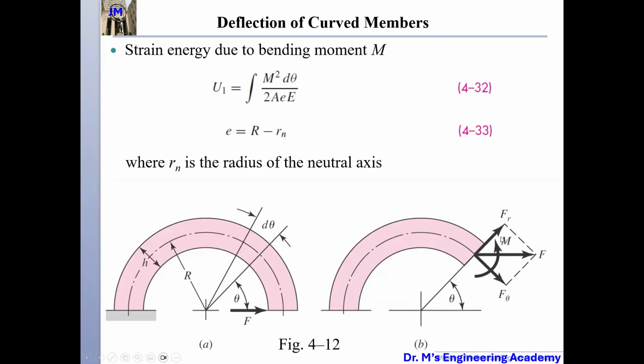So all these I r, I theta, and I am along with this I theta, because when we decompose this I into I theta and I r, the point of entry we move to the centroidal line. Okay, centroidal line, that means it is different from the neutral axis. As a result, this I theta itself will generate a bending moment.